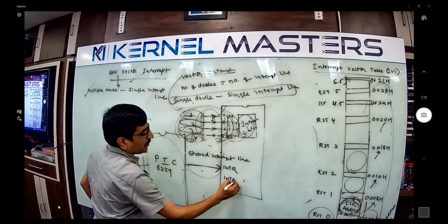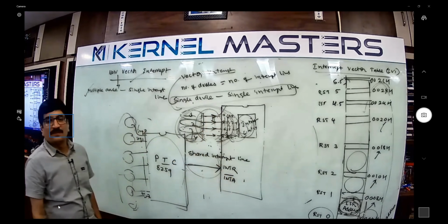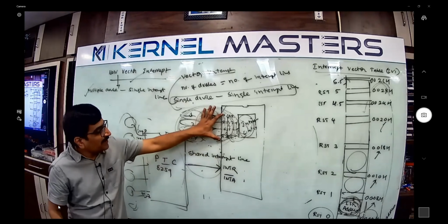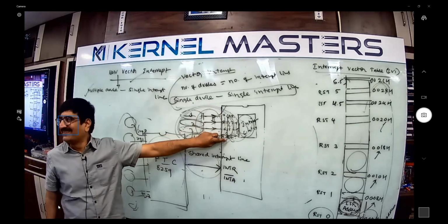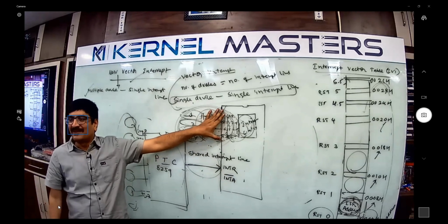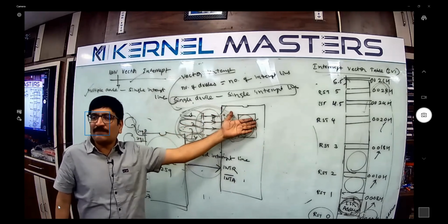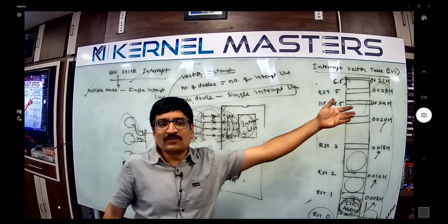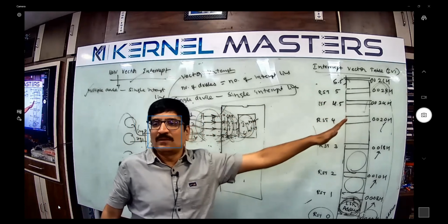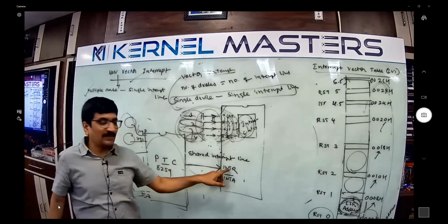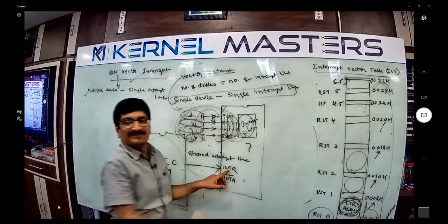I think I told you about one signal. Everyone remember now? The INT acknowledgement signal. For these 4 interrupts, is there an acknowledgement or not? No acknowledgement, because they are vector interrupts. Whenever these interrupts occur, the microprocessor has clear information, so it goes and executes. No question at all. But whenever this interrupt occurs, the microprocessor has a question mark, no?